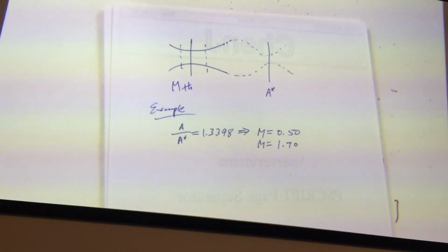If you have a shock wave, your stagnation pressure will be lost. There will be a decrease in stagnation pressure. Stagnation pressure, in a sense, is the total ability, the total capacity the gas will have to work. And part of the work is expansion.